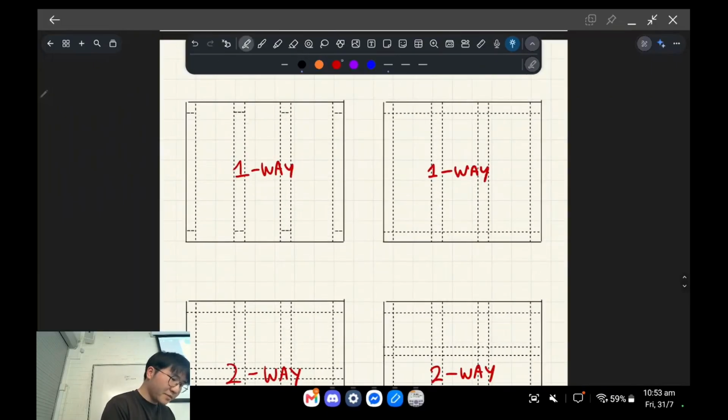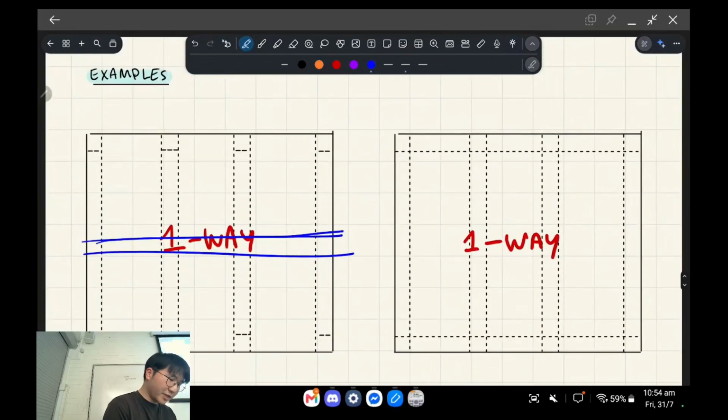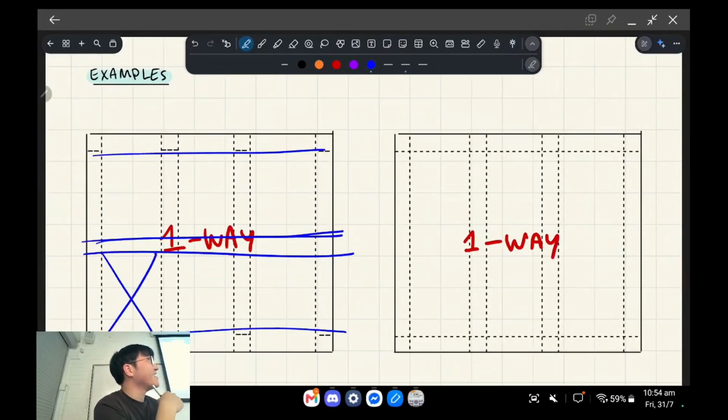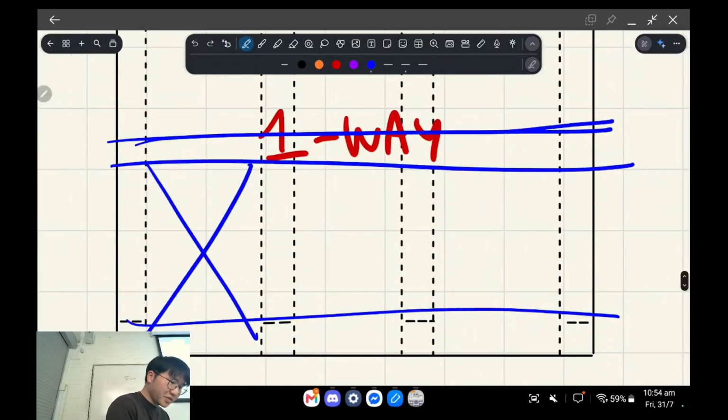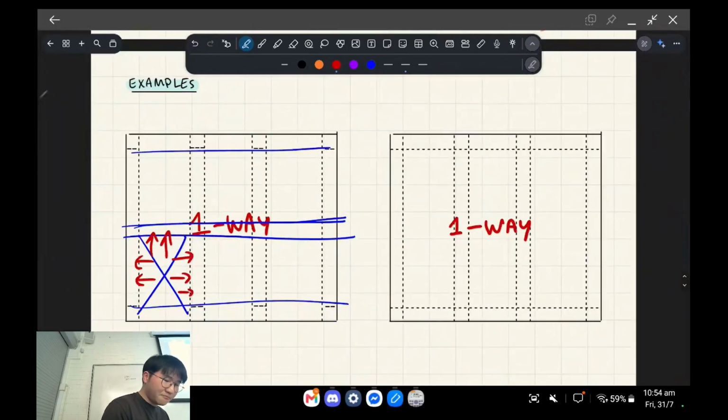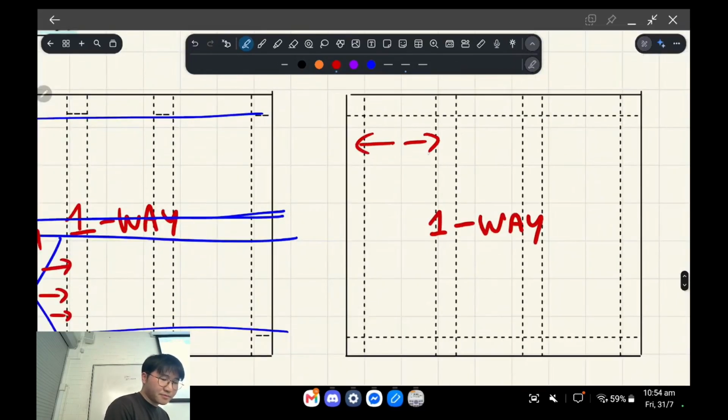Okay, so you have beams that break up these individual rectangles, right? So this is from a top-down view. And when you have beams that form an almost square shape, in terms of these bays, the forces distribute into the beams like so. Whereas for the case of a one-way slab, the forces go in one direction, from the slab to the beam.